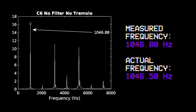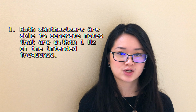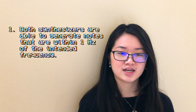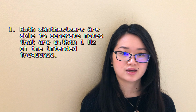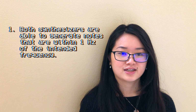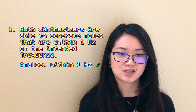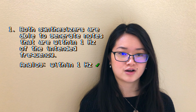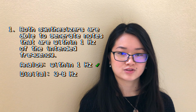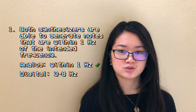From this data, we can verify our success criteria. Our first criterion is that both synthesizers are able to generate notes that are within 1 Hz of the intended frequency, as the average human ear can only begin to discern different notes around 3 Hz. Though we have no recorded data, the analog synthesizer was always within 1 Hz of the expected frequency, as we visualized on an oscilloscope. The digital synthesizer was on average 3 Hz off, with a maximum difference being 8 Hz off, but this could be due to the low fidelity of audio recording as opposed to directly measuring off the board with an oscilloscope.